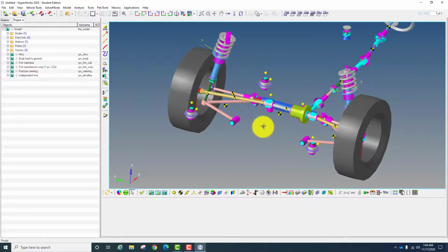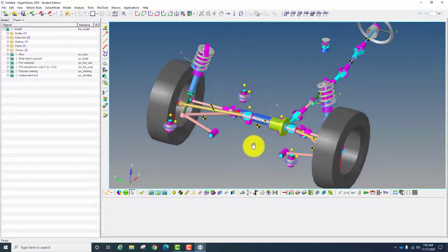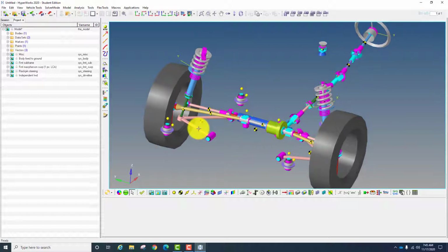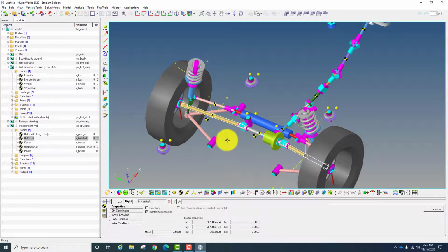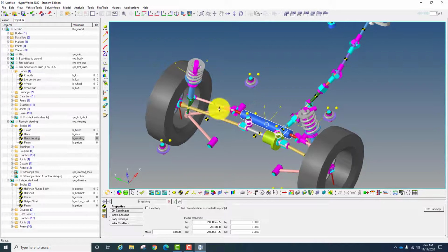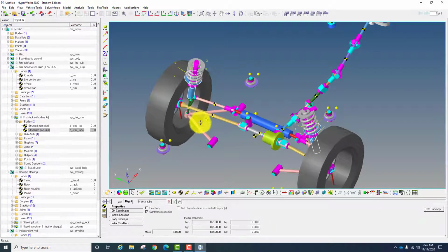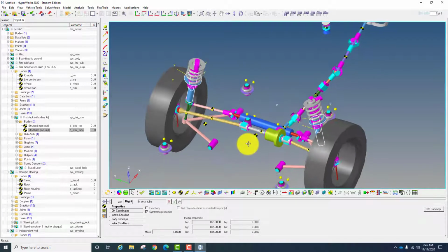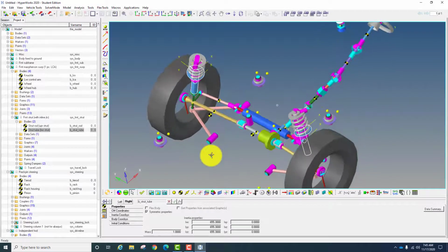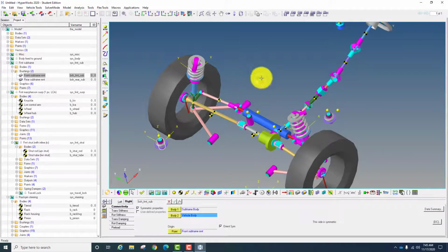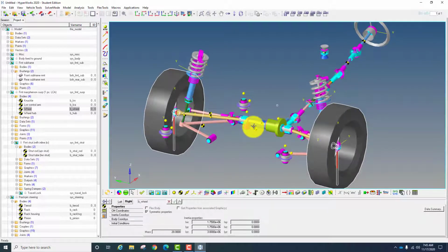What you see in the MotionView model, since you chose the McPherson strut, is one piece of the lower control arm here. You have a driveline here, this is the driveline. You have a steering system here, rack and pinion. We have a strut, which consists of the spring and dampers. We have a subframe here, this is a subframe mount, and this is a wheel.